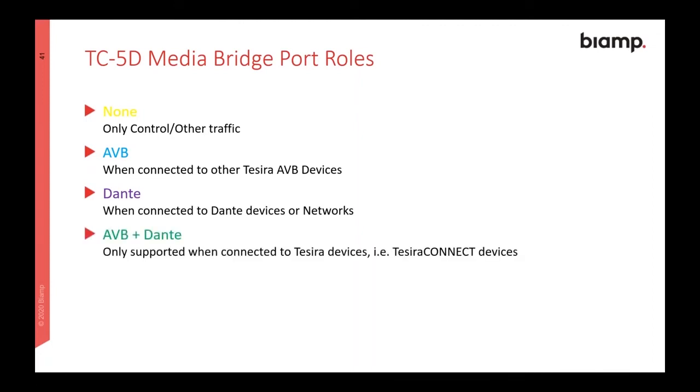We do support a mixed mode where it's doing both AVB and Dante, but the big flag is that it's only supported between Tesira devices. As I mentioned, both AVB and Dante being real-time protocols require the highest level of resources, bandwidth, and QoS settings. So there'll always be a conflict between AVB and Dante.